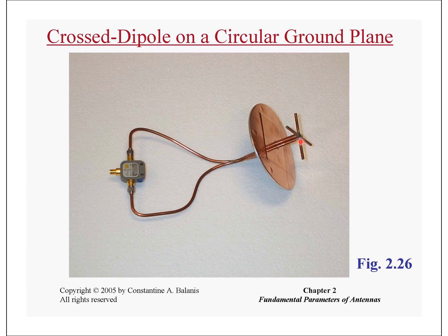Now the connections are straightforward: the outer conductor of the coaxial cable is shorted to the ground plane, and the inner conductors of the coaxial cable are connected to the dipole elements.